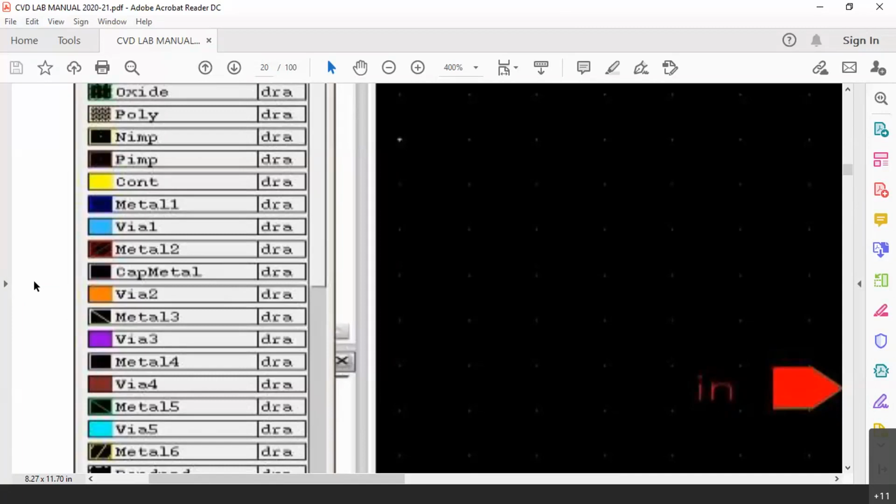What does it mean? There is a flyover, over flyover, over flyover. Now in our physical city, in between two flyovers, it is simply a space, or simply air blowing there. But what about inside the chip? Inside the chip, everything is solid material. So if there is one metal, above which one more metal layer is required for making connections, the gap between the two metal layers cannot be left empty because it is completely silicon, a completely solid crystalline structure.